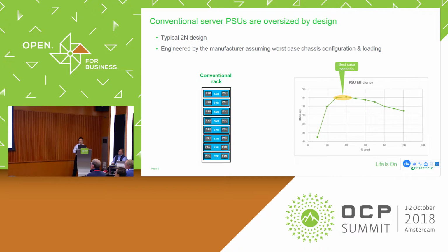At the same time, when we design power supplies, lots of companies are developing them, and we consider efficiency; we heard about platinum, titanium. The best point is going to be 40 to 60% of the total loading on the server. That's going to be the best scenario for power efficiency.